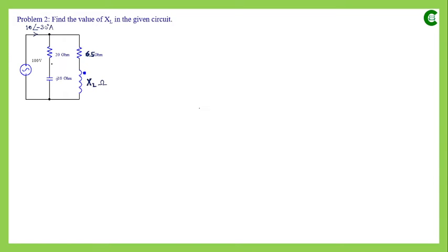In this branch, a resistor and capacitor are connected in series, and their resistance and capacitive reactance values are given. And in this circuit we have the resistance value, and this inductor and resistor are connected in series, but the inductive reactance value is not given, rather it is represented by X suffix L. And this parallel branch is energized by an AC sinusoidal voltage having value 100 volt.